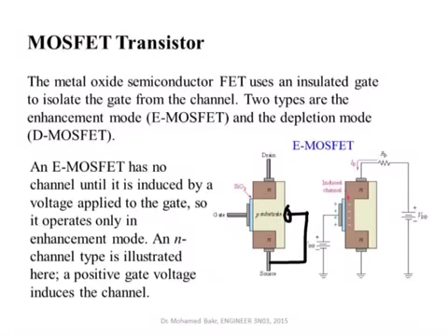Now, this is also called an enhancement MOSFET, because when you have VGS equal to 0, when you don't apply any voltage, there will be no conduction happening because there is no inversion channel or conduction channel being created. But in some other types of transistors, when there is 0 voltage, there are actually some electrons existing.